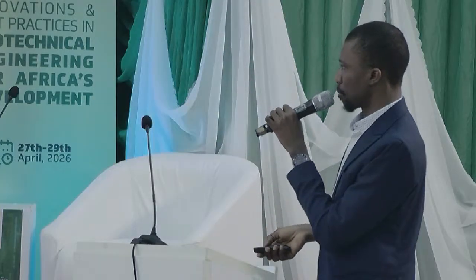Now, these are the mechanical parameters because, as I mentioned earlier, we are trying to do hydromechanical modeling. We already have the hydraulic parameters. Now we have the mechanical parameters. For the Mohr-Coulomb model, these are the simple parameters. But for the Barcelona Basic Model, we have a lot more parameters.